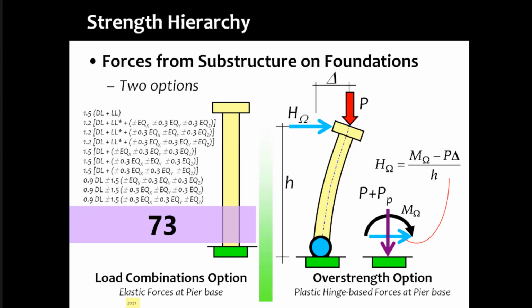So the load combinations, there are so many load combinations for us, and they are listed in the standard. All of that apart, you still have to do one more combination, which is related to the overstrength option. And this is how you will save your bridge. So the classical load combinations will not save you because those are all force related, and the displacement related story is coming in the overstrength load combination, which is specified nowadays by the bridge codes explicitly.